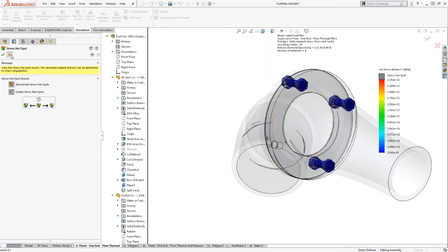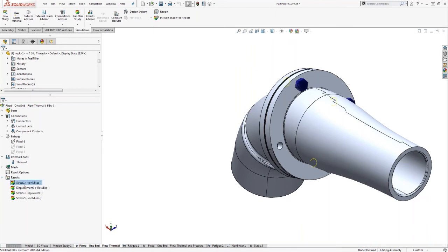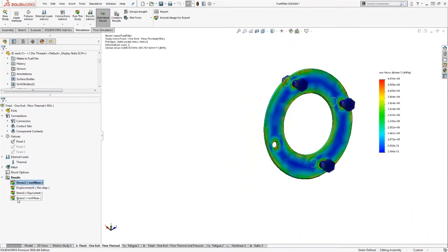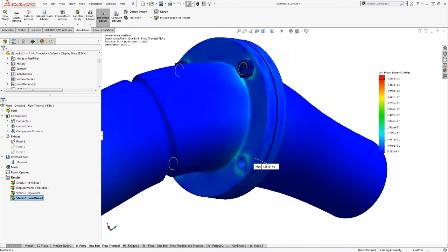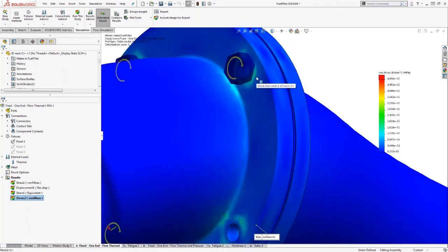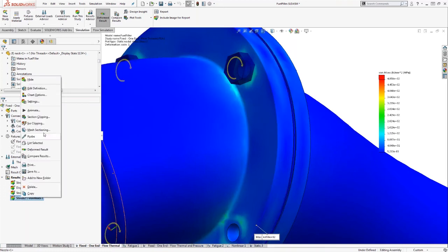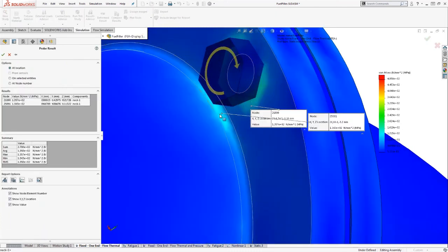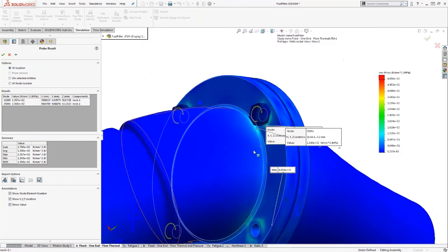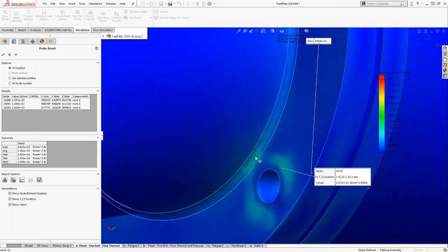But everywhere else in the model, everything seems to be okay. You see that the stresses happening within the overall geometry, we're not expecting too much. Right now we're just gauging it based on the color scale. But if I specifically wanted to know what the stresses were at a specific location, I can go into my stress, go into the probe, and start clicking everywhere that I'm concerned about. And you see that it just gives me these probe labels here.